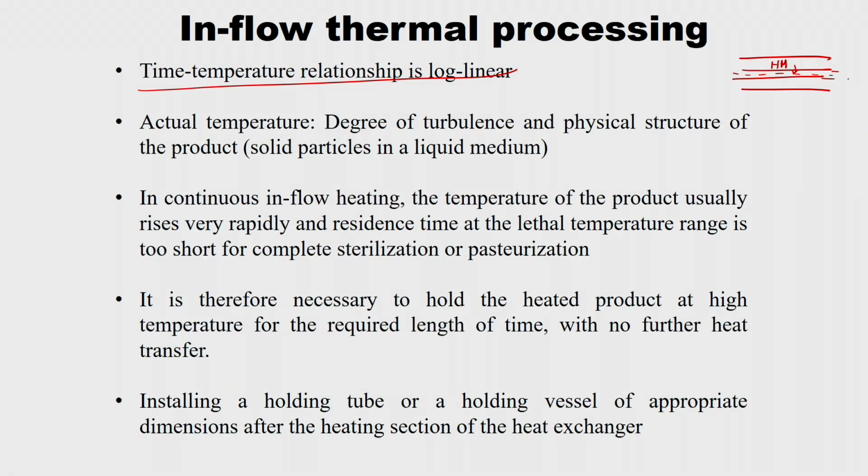So, this also follows a log linear relationship, but the actual temperature depends on the degree of turbulence, whether any turbulence is there, and the physical structure of the product I already told. If it is completely solid particles, or a suspension of solid particles in liquid medium, it will have different properties. And in continuous flow heating, the temperature of the product usually rises very rapidly. So, residence time in the lethal temperature range is too short for complete sterilization. So, what happens is your resistance is small, so your temperature rises rapidly.